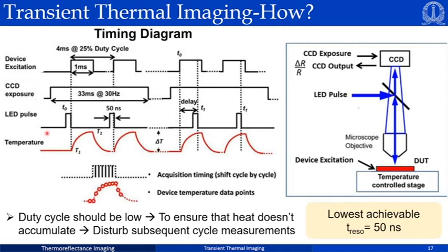And at each LED shining, you are measuring the reflectivity, and therefore you will capture temperature at each and every LED time instance, right? Whenever the LED shines, you are getting the temperature. Therefore, what can you do? First you have to capture just at the edge of the electrical bias, that is, just before the electrical bias is applied. Let us number it as T0.